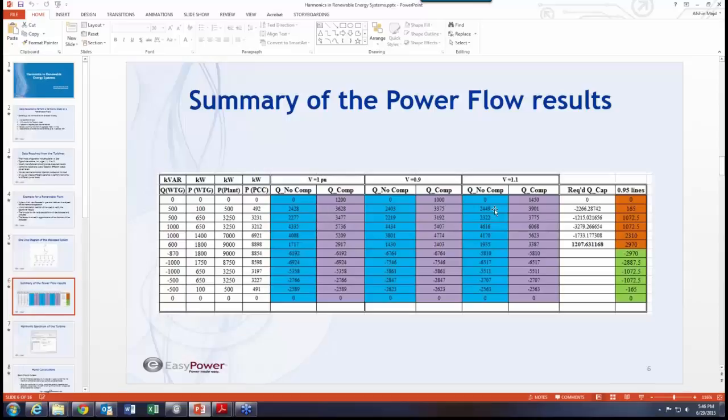So if somebody adjusts the voltage of the utility, you would be able to extract more reactive power out of the same plant with the same turbines generating all the same value of Q. So it's an interesting fact, but not necessarily related to this webinar, something that we as power engineers know very well: the reactive power and the magnitude of voltage are directly related. So when I change the magnitude of the voltage, you would see the plant generates a different amount of reactive power.